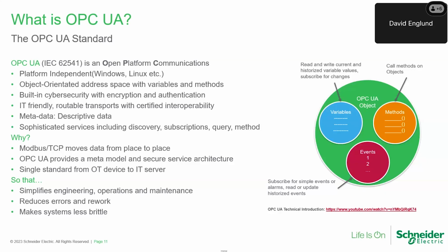Consider the OPC UA diagram on the right. We can think of this object model as a digital blueprint of a factory. Objects represent real things. We have variables for holding information, like the value of an analog input. There are methods that can generate actions, like moving a robot to a specific XYZ coordinate. There are events for notifications. This would most commonly be an alarm. And we also have metadata for data contextualization. This would be something like a timestamp or engineering units.